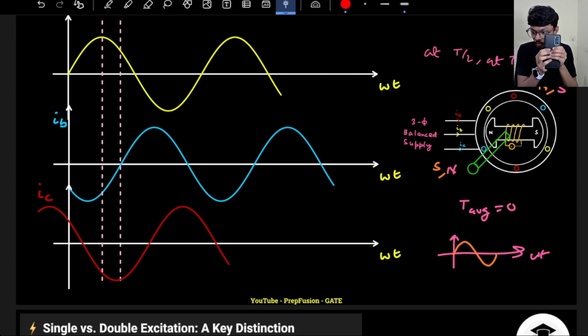So actually it will never rotate. Why? Because remember, your rotor is a very heavy object, and your stator magnetic field is rotating very fast. The rotor will not be able to react due to inertia. Once both the magnetic fields are coupled, then they will synchronize, and they will move together no matter what. But during starting, this will not happen because the stator magnetic field is very fast. Due to inertia, the rotor will not move.